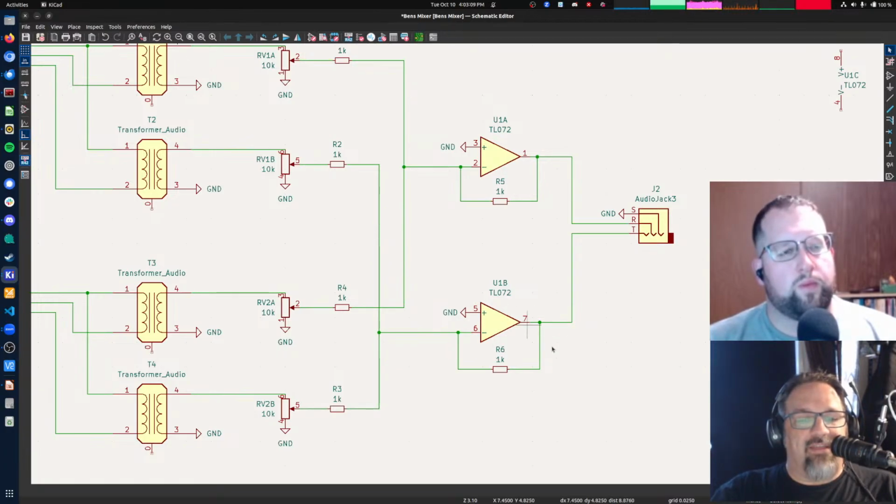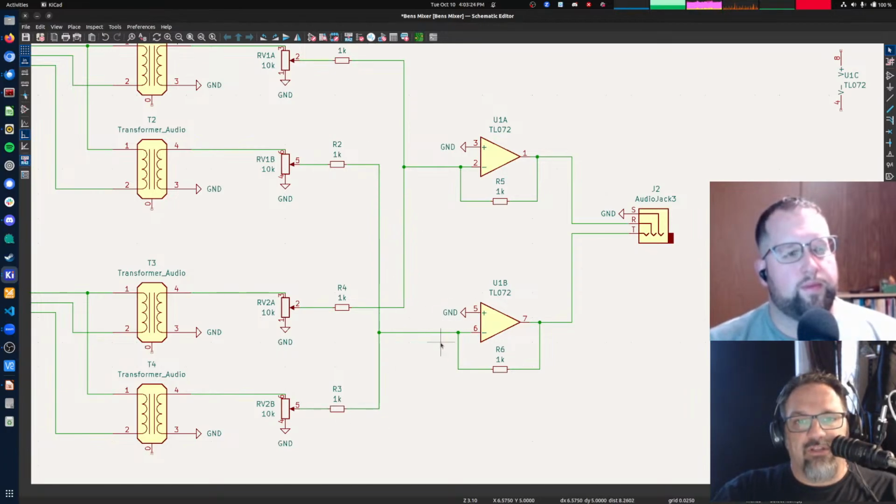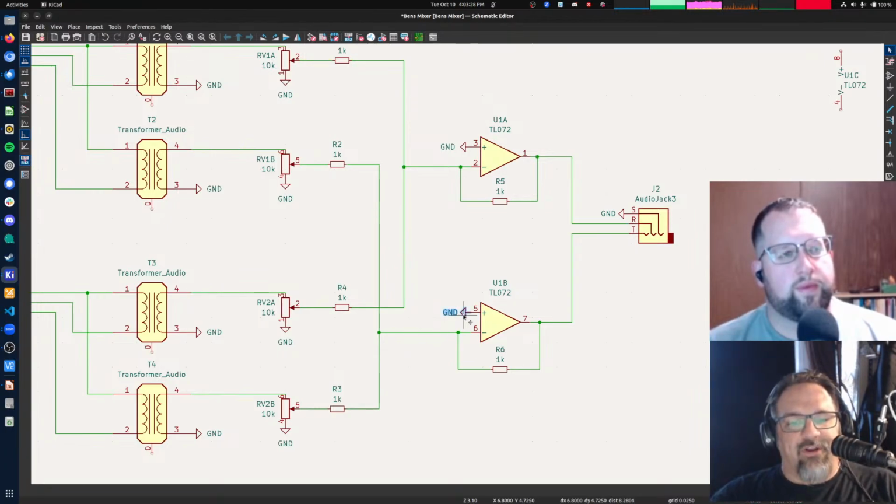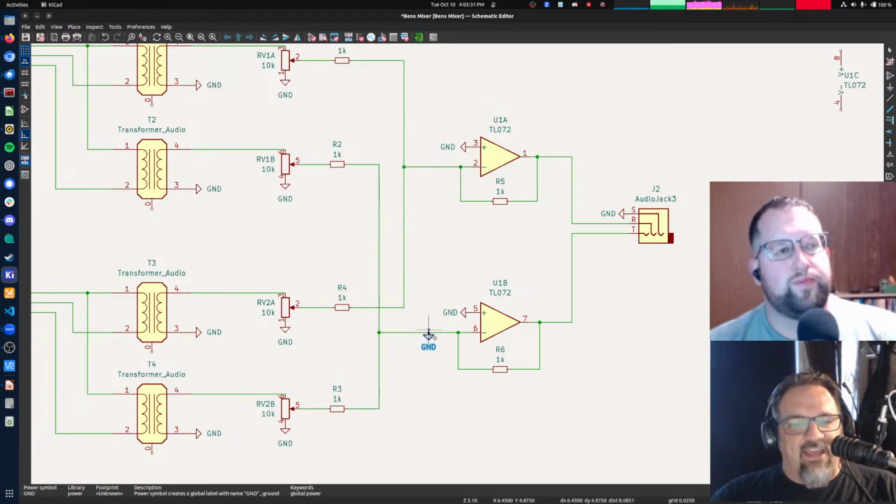So this op amp in this configuration will consume all of these currents and do whatever voltage is necessary on the output to prevent those currents from flowing anywhere else. This node is as if it were ground. You can literally view it as if I were to take this and tie it to here.